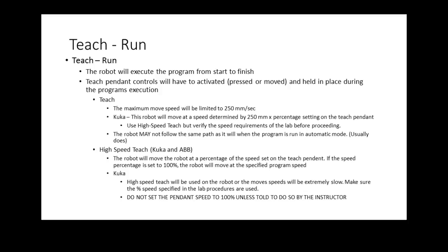High-speed teach doesn't come into play when you're jogging the robot. High-speed teach comes into play when you put it in teach run. So when y'all saw me run the big FANUC over there, that was full speed. That was high-speed teach. So we got to be pretty careful.